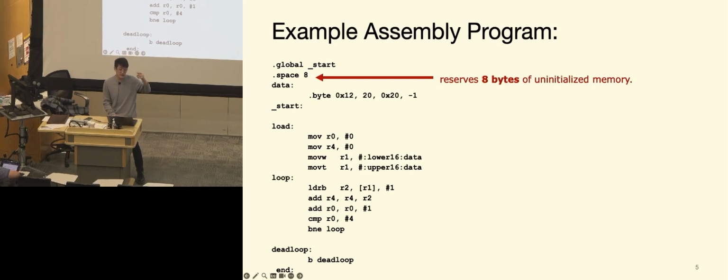If we assume the whole program starts at memory address 00000, which is usually the case when it fully boots up on an embedded system, then the first byte of data is reserved with no data in it, and the data, which is the bottom four bytes, is going to be put at address 0008. Hope that clears up any questions from last lecture.